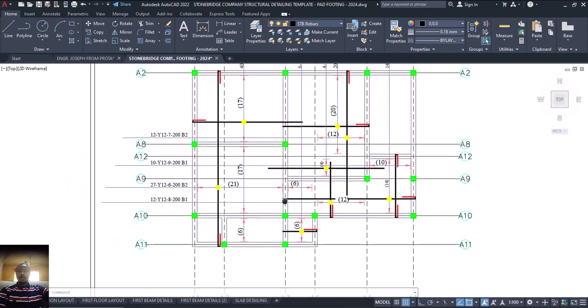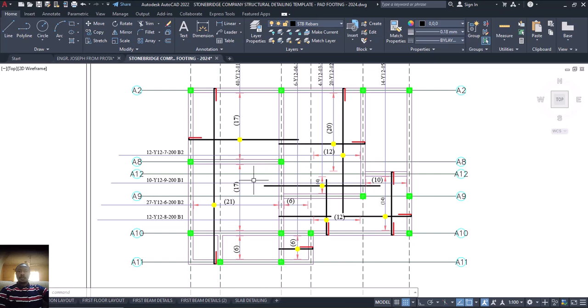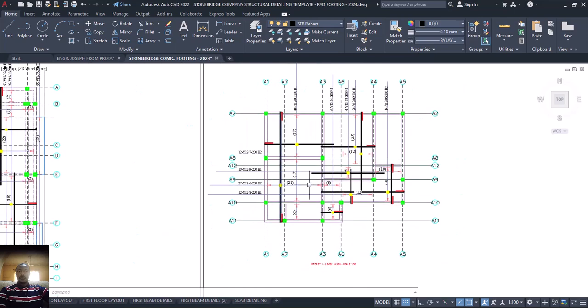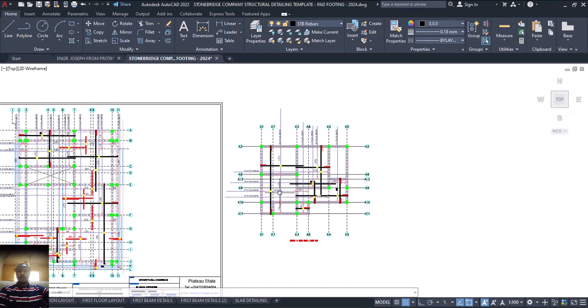What remains is the top reinforcement, which is along this place, or the hogging moment reinforcement. That's top reinforcement, T1 and T2. Based on this, we can do all the T1 and then indicate T2, which is to be used for other T1. So that will be in our next video. Is that okay? At this point, I want to say thank you.